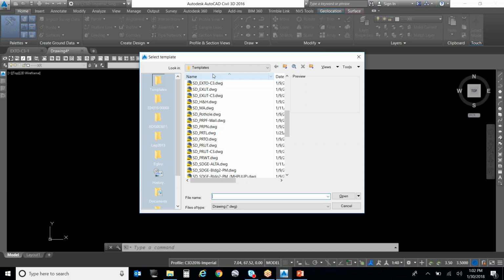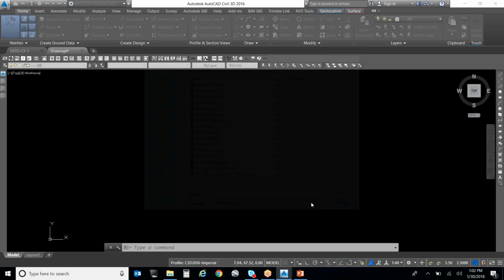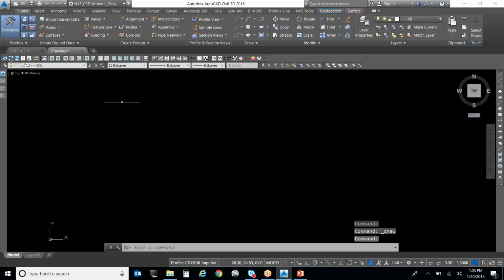Anytime you receive a file from outside this office, open a new drawing from our appropriate template and insert that drawing in. Why do we want to do that? Because if they have a pre-Civil 3D, it comes in international foot. All right, that's a good answer. That's one answer. What's the difference between an international foot and U.S. survey foot? Why is that important?